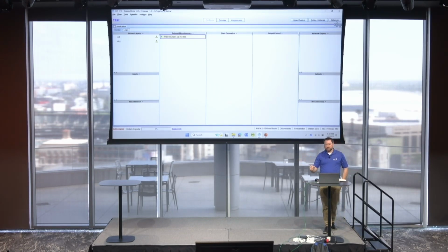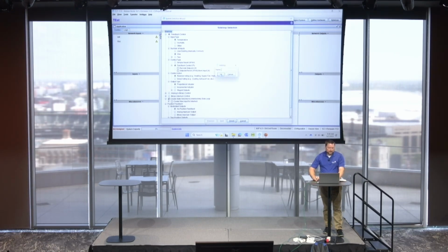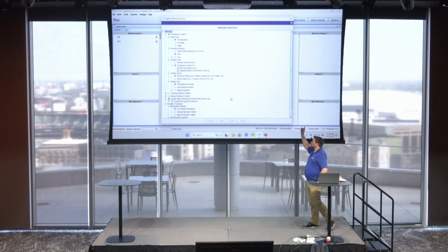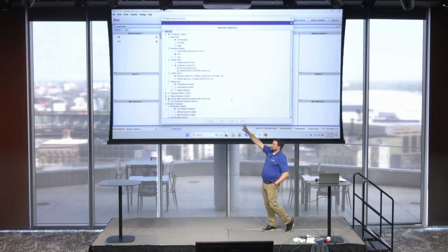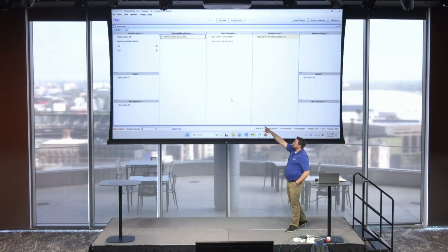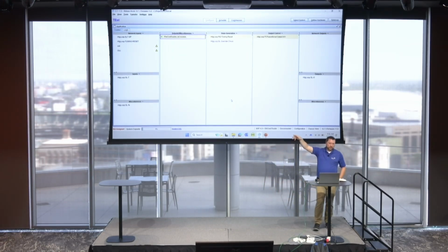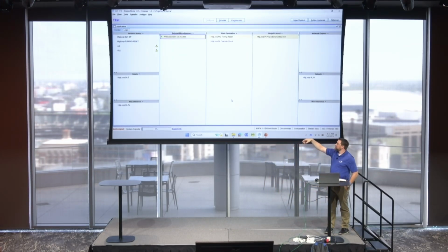I'm going to create a PID, right? Create a PID. Call this my heating loop, and it builds a couple things for me. It'll build my output, it'll build my process variable, my input, it'll build a couple of points, a tuning reset, because we have an auto-tuning PID loop, our PRAC, pattern recognition adaptive control, and it creates the PID as well.